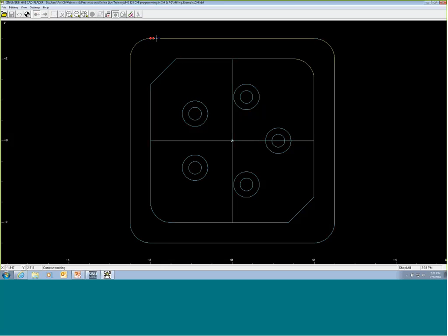Okay, so I click the same feature a second time, and now I start to look. See what it's doing is it's kind of guessing and trying to pick different locations. I get all these crazy picks. Well, that's because I have not gone back and adjusted an appropriate catch radius. I'm still seeing it at 1 inch. So that's where this becomes very important. So I'm going to set mine to maybe 5 thou. All right. Now we go back. It will retain the name of the last one until I'm done with the contour. All right. So let's go repick.